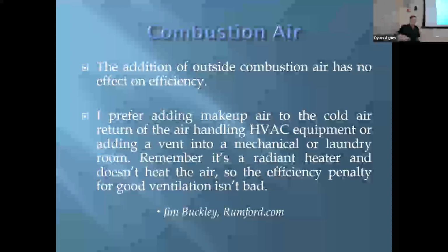By the time it gets to the fireplace and goes through the room, it's basically tempered. It's going to be ambient temperature. And so I've tested the theory. The way I did it is I put temperature monitors in the ducts closest to the furnace, closest to the outside, and furthest away. And I wasn't getting cold air coming out of a duct. It was tempering as it moved through the whole system.